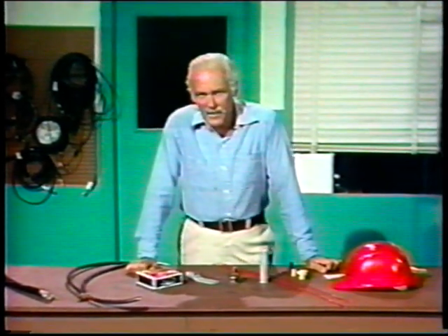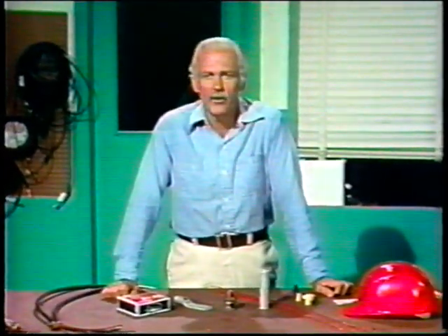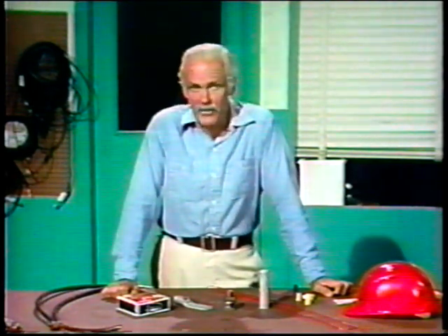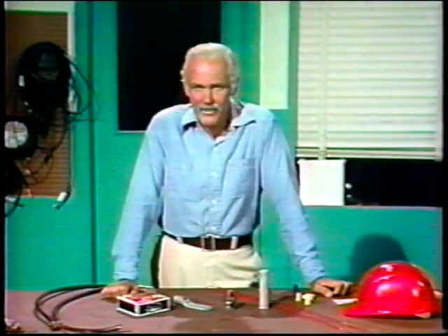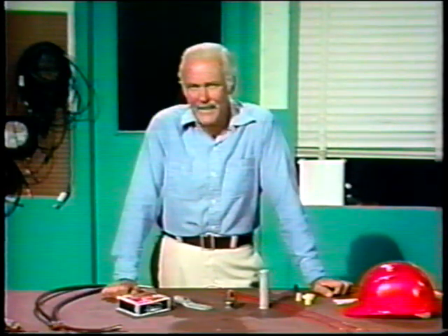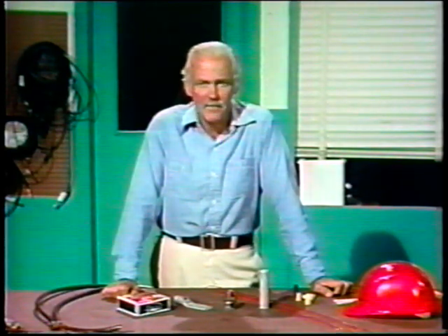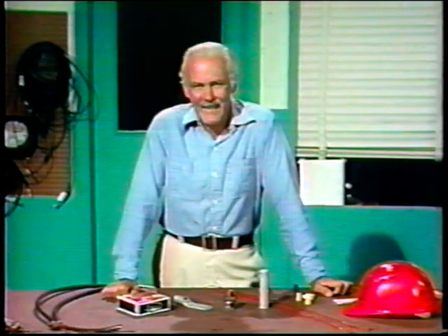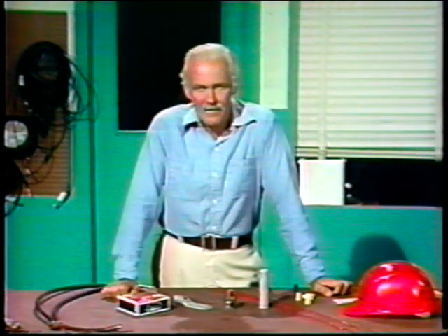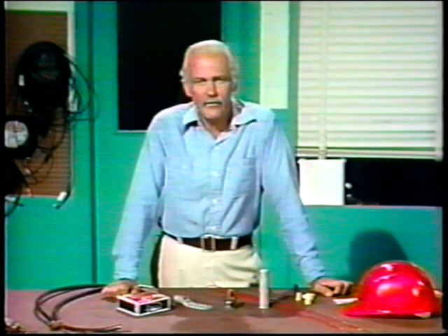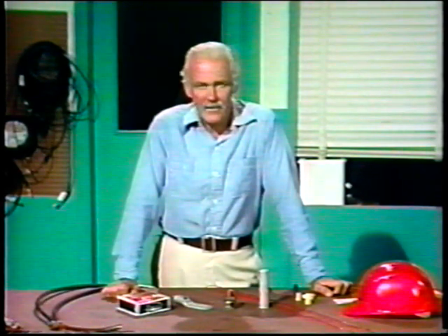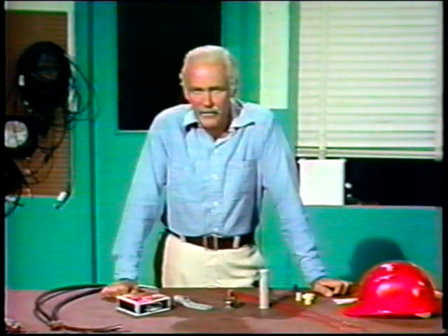A splice is a point at which two or more conductors are connected together to extend the overall length of the conductor, or a point at which two or more conductors branch out from a conductor. There are several kinds of devices used to connect the ends of conductors together within the splice. For simplicity's sake, we'll refer to these devices as connectors for the time being. Connectors usually fit into one of two categories: thermal connectors and mechanical connectors. Let's briefly discuss thermal connectors first.